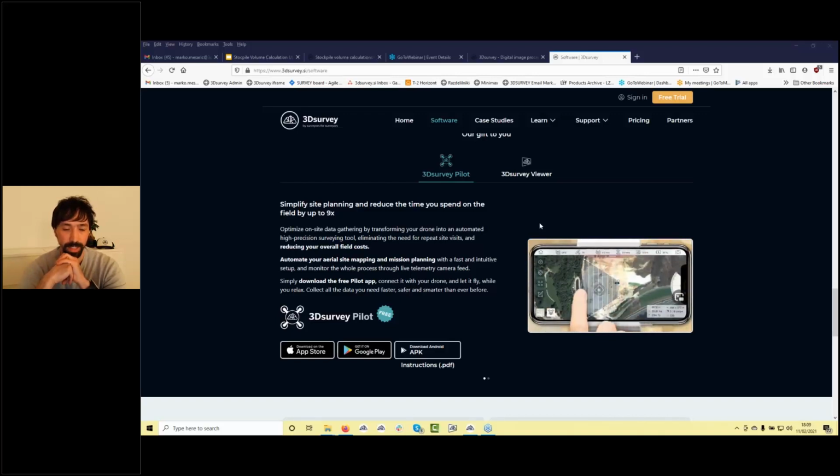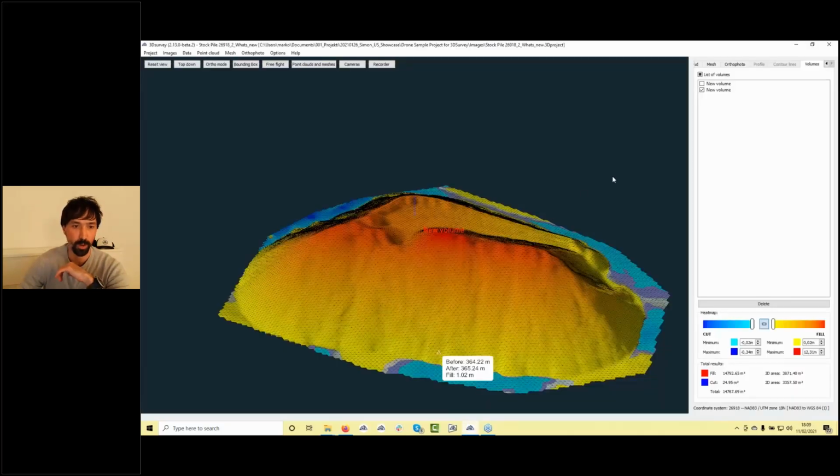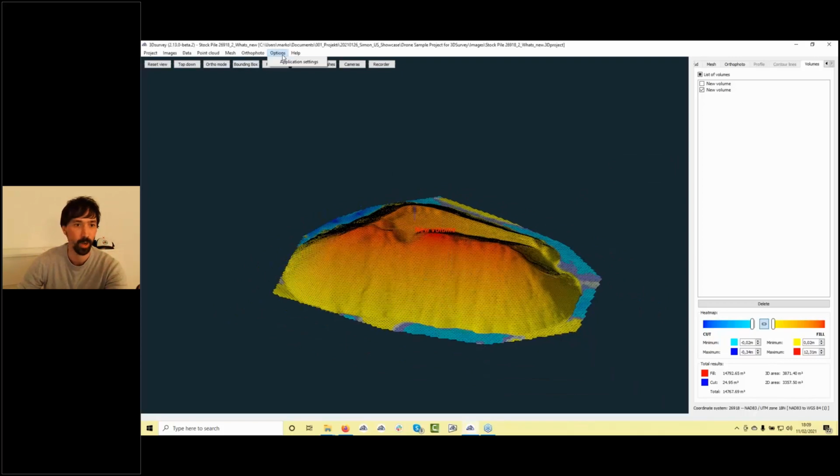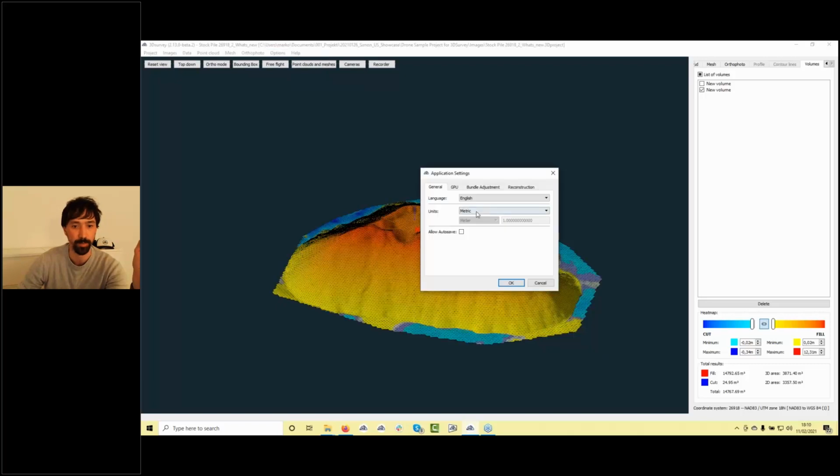Okay, then another from NG Young Lee. Can volume units be changed when needed? You can see how I change the volume units. The problem is everything is calculated from the data, so you need to change it in general settings, option, application settings, and go to Imperial or metric. When you go to Imperial, you have two options, US feet or other, or actually three options.